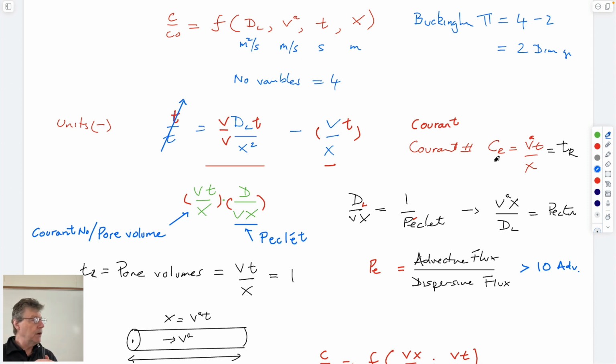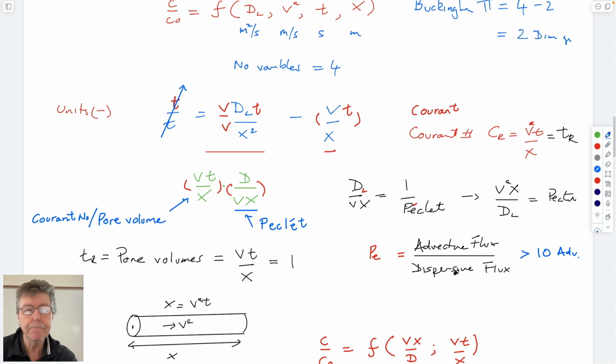And so in numerical methods, if you use an element to look at solute coming in and going out the other side, if it goes right the way across the element in one time step, then that element hasn't seen that stuff go across it, and so the model will blow up. It won't give you a decent result, and so it's used for that.